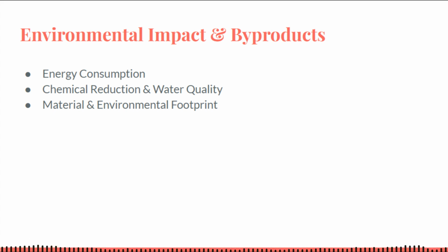From an air quality standpoint, especially for indoor pools, reducing chloramine off-gassing by using ozone or AOP dramatically improves the indoor air environment, a health and environmental win. In summary, ozone and AOP systems strive to minimize harmful byproducts in pool water. By preventing chloramine buildup, they not only make swimming more pleasant, but also reduce corrosion of indoor ventilation systems and irritation to the environment.